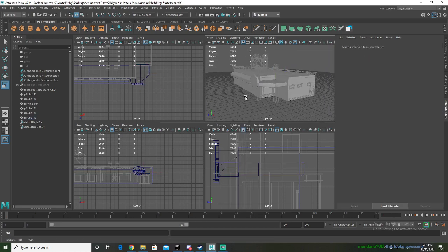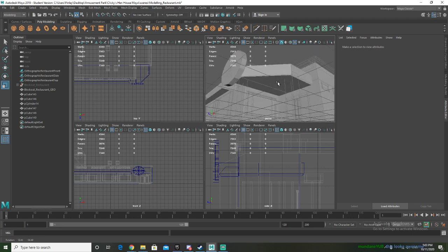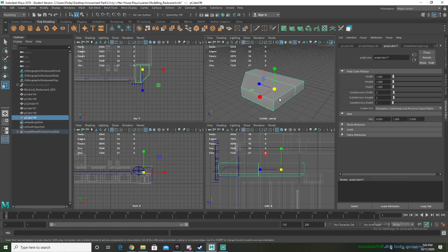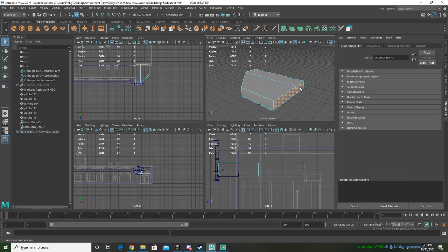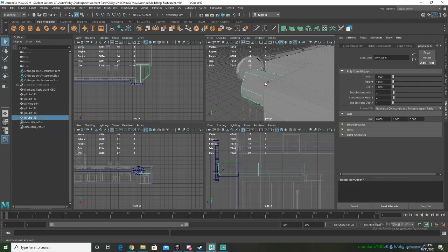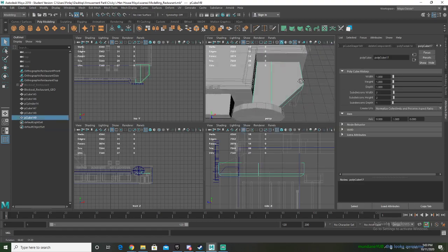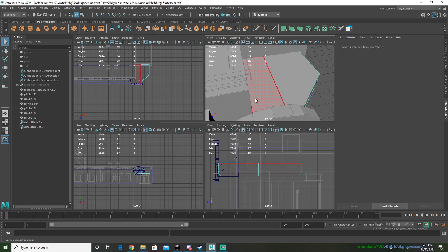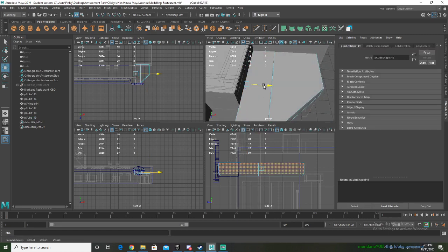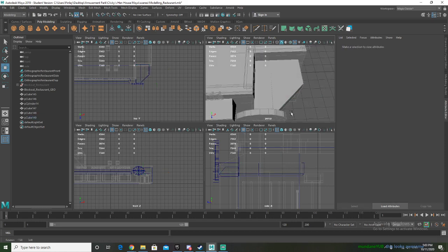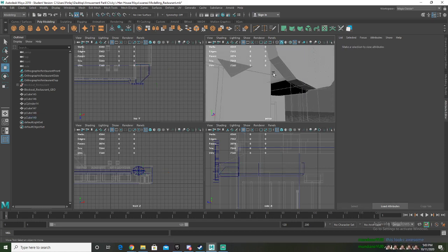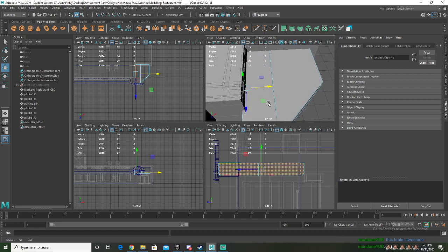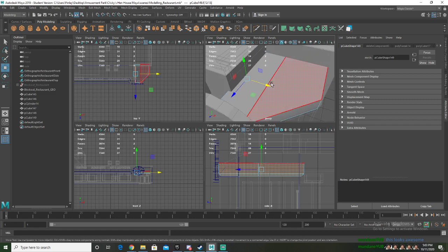Basically give it something sort of like that, and then make it slightly more interesting to look at. And now, Control 1, select these two faces, and delete them, as they'll never be seen. We don't want to waste polys on having them actually be rendered. What I'm going to do quickly is add this face slightly so it's intersecting with the building. Actually, what we need to do, add both these faces and make it go a bit further so it fits with the original, like that. But yeah,